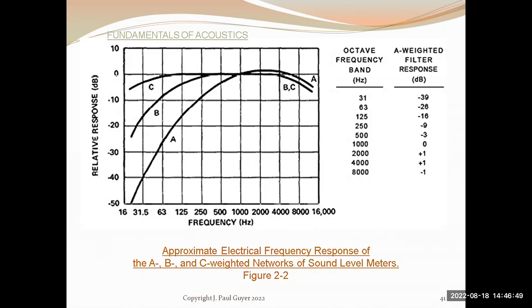And they represent the fact that the sound level meters will, depending upon the setting, filter out or discard or not record certain sound that is being perceived. Like the A curve that you see here, this corresponds to the A curve on this knob. And so you see that between about 500 hertz and 5,000 hertz, the sound level meter records and displays just about everything that it perceives.